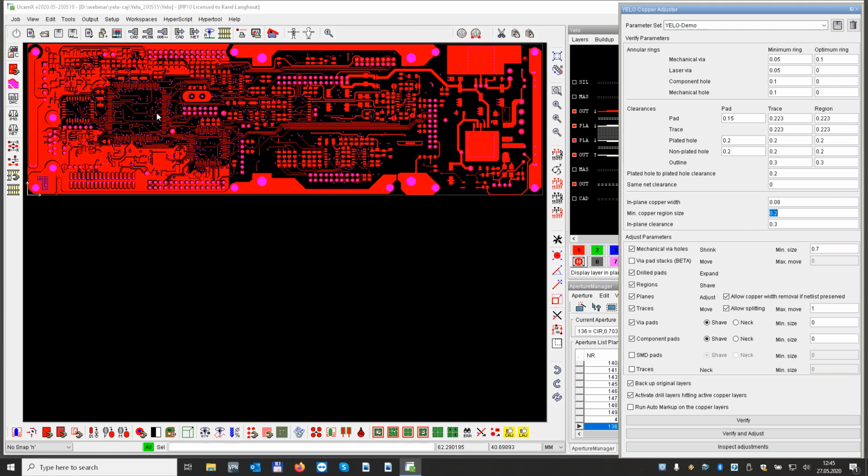It's quite simple. It should be smaller in X and in Y. So if you have something that is 0.1 wide and let's say a millimeter long, then actually it will not be removed. It will then look at this value, the 0.08. So that means if it would be 50 micron wide, it would enlarge it to 80 micron, but it would still be a millimeter long, but it does not get removed. Okay. So I think that answered it.